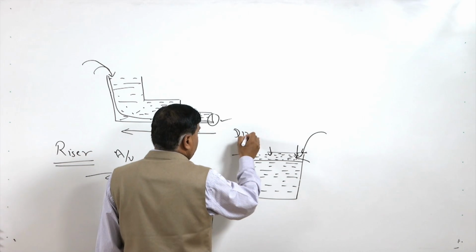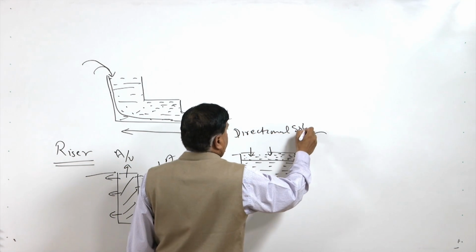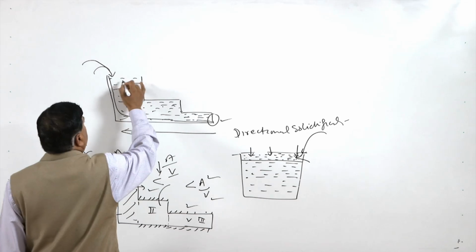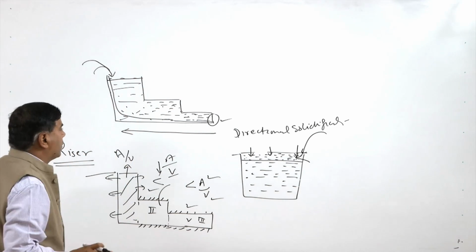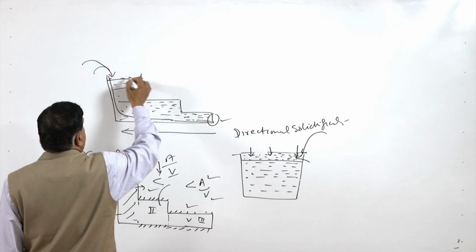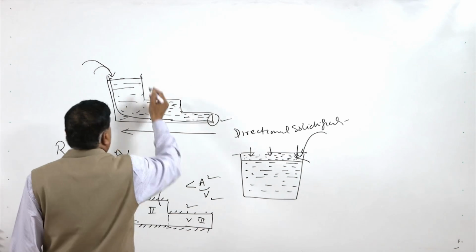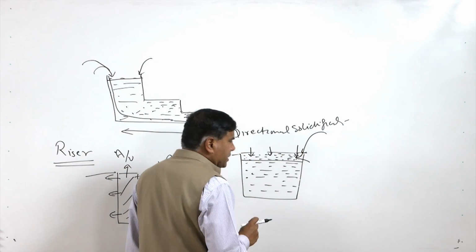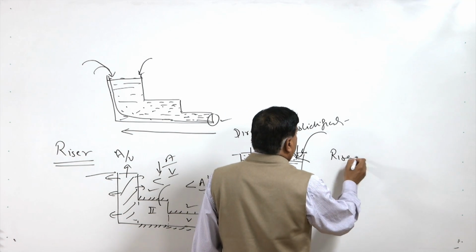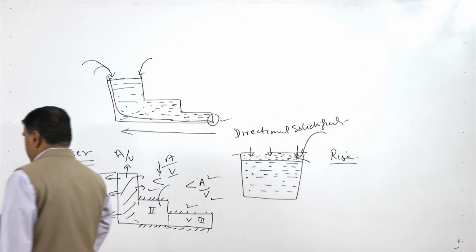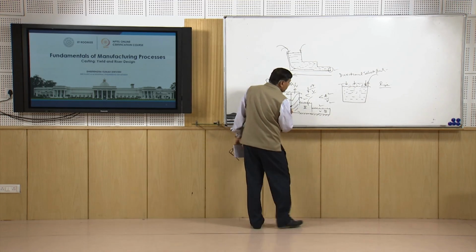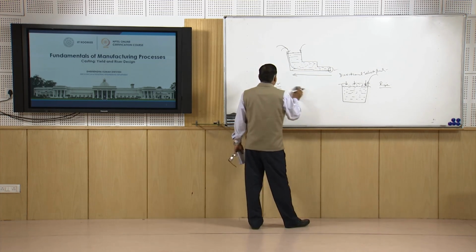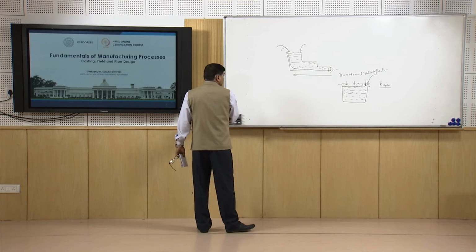This kind of solidification is called the directional solidification. And in this case, if any shrinkages will be occurring, then that will be occurring near the feeder, which can be effectively fed by the molten metal either coming from the feeder or from the ingate or from the riser. So, any such kind of the shrinkages can easily be taken care of by the riser if the proper temperature gradient is maintained. But in those cases where proper temperature gradient is not maintained, means the solidification does not remain directional, in those cases some other kind of the issues are encountered.